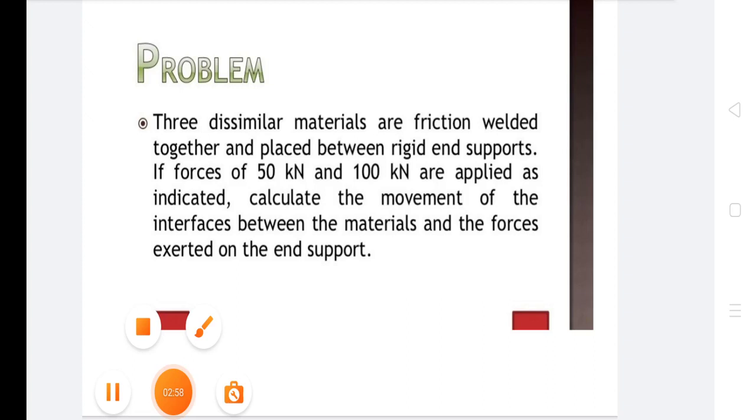After this, we discuss assembly of element equations to obtain the global equilibrium equations. As the continuum is composed of several finite elements, the individual element stiffness matrices, displacement and load vectors are assembled to obtain the global equilibrium equation. The global equilibrium equation is given by K Q = F, where K is the global stiffness matrix, Q is the global displacement vector and F is the global force vector.